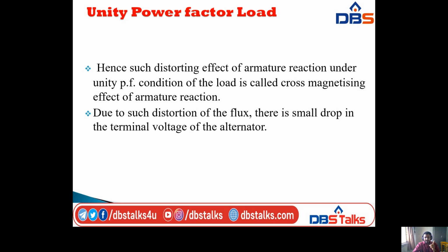Hence, such distorting effect of armature reaction under unity power factor condition of the load is called cross magnetizing effect of armature reaction. Due to such distortion of the flux, there is a small drop in the terminal voltage of the alternator.